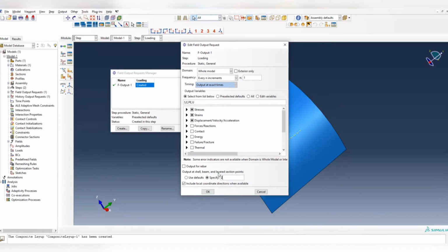If you have 2 layers, then you also probably want the fifth integration point, which means 2 plus 3. And also, if you have 3 layers, then you have 2, 5, 8, another plus 3. Now keep doing that. You should have 11, 14, 17, 20, and keep moving on. Well, right now we only have 1 layer, so only 2 is available here. But we can enter how many layers we want. So let's do 23. Okay.